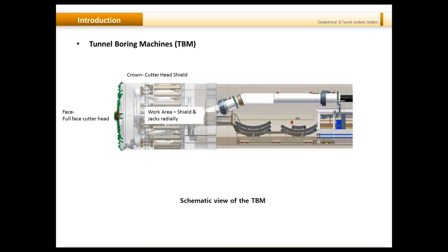So usually what happens is that when you hit a soft ground and it's a fault plane or something, that it mobilizes the entire rock strata around it, then if you're dealing with drill and blast, or if you're dealing with other conventional methodologies, then your workforce is highly at risk. So this shield alone avoids any kind of fatal accidents.